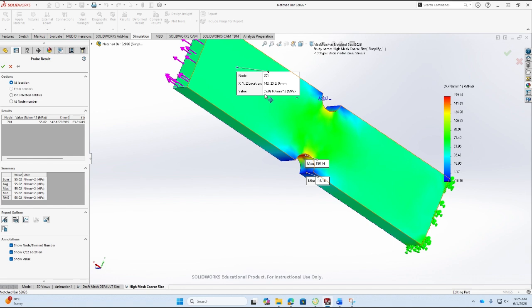And sir, what do we rely on, which mesh? Yes, which mesh? That's what we are going to find out by doing this convergence study. It depends on how much accuracy we want from our analysis. If you have a very complicated, huge part and you try to use a large number of elements, computationally you may not be able to solve it. Right now you will be able to solve all of these cases, but practically it's a judgment call.